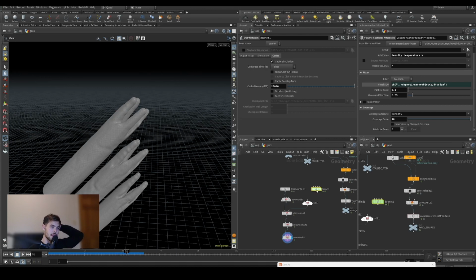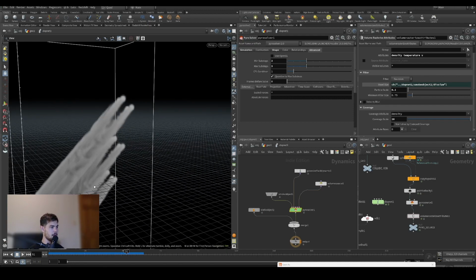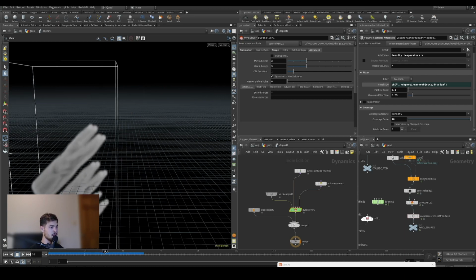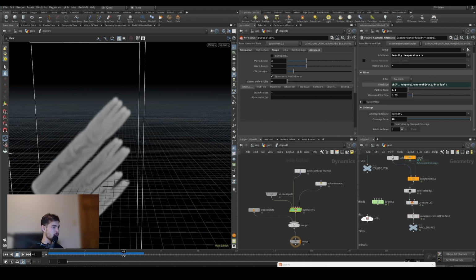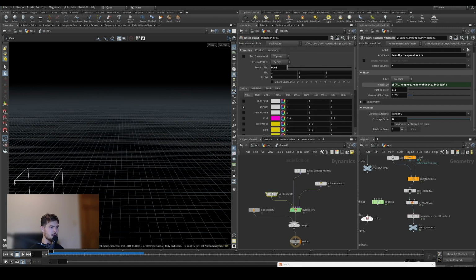And so I think one thing that's really helpful is increasing the substeps in the solver. So that helps to smoothly emit the smoke into the simulation and allows for just greater density to accumulate, I believe. So that seems to be really helpful.